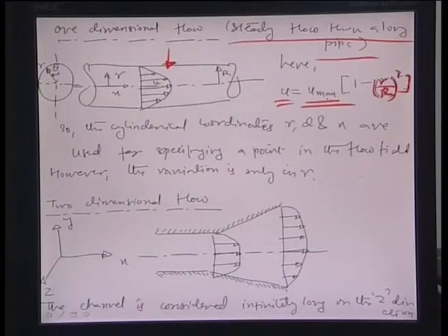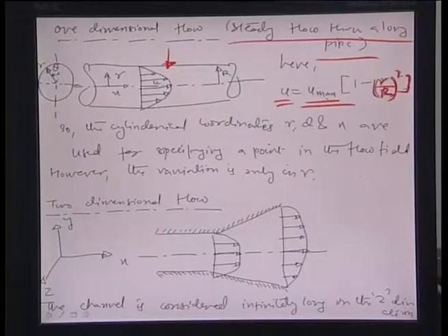So, typically this is the case in cylindrical coordinates. The same is true for the z direction. The z length is too long in comparison to the radius of the pipe, and so if you are talking about microflows where the dimensions of the pipe itself are very small in comparison to the length over which it is laid out, you can typically consider it to be a 1 dimensional flow problem, which is radially symmetric, if you assume that the continuum approximations hold true.